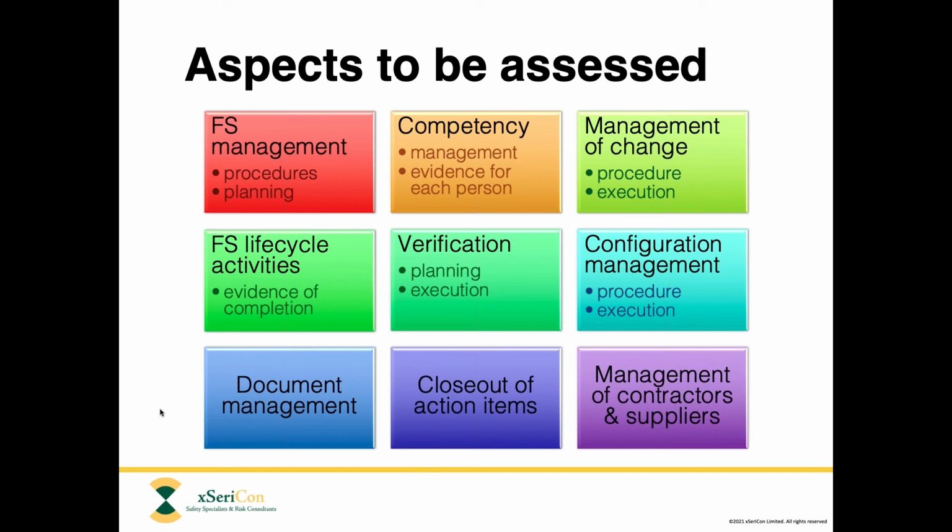Number 6 relates to configuration management. So the idea of this is, again, at a certain point in the life cycle, you're supposed to freeze the configuration of each safety instrumented function in terms of, for example, the number and the design of the hardware that's used, the parameters such as the proof test interval, the proof test coverage, the designated lifetime for the equipment, and so forth.